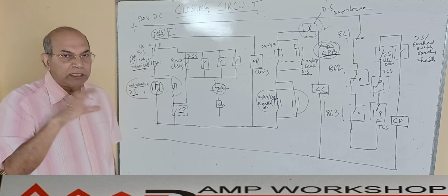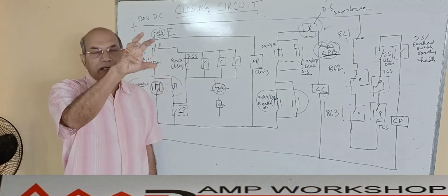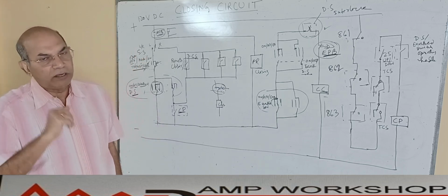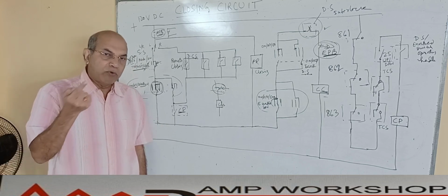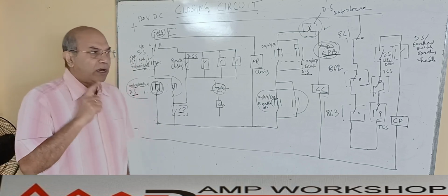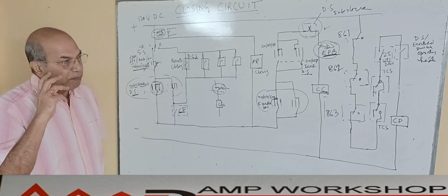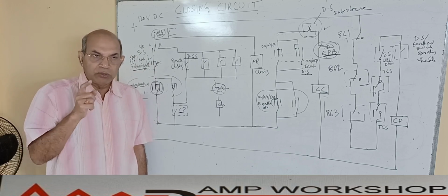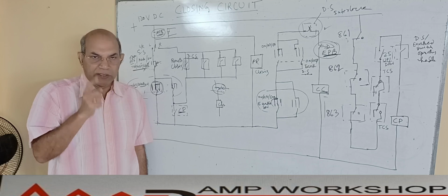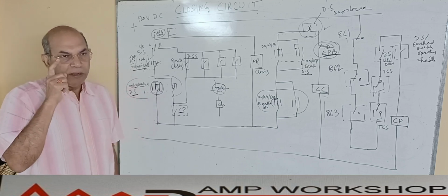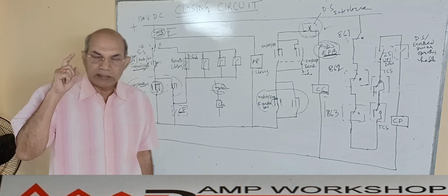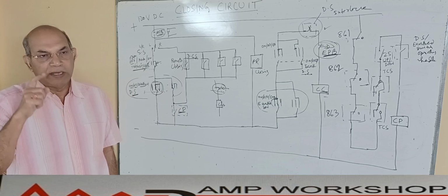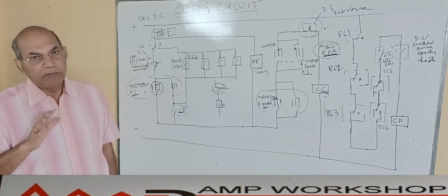But when I am local, the trip coil supervision relay is on the panel, and I can see whether the relay is healthy or not. When I am remote, I am not able to see this, so that interlock is required. That means when I am closing the breaker from the remote, I have to get permission from various parts of the system, to ensure all the parts are in healthy condition, and that if I close the breaker and any sudden abnormal condition comes in, the breaker has enough strength to trip. That I have to make sure.